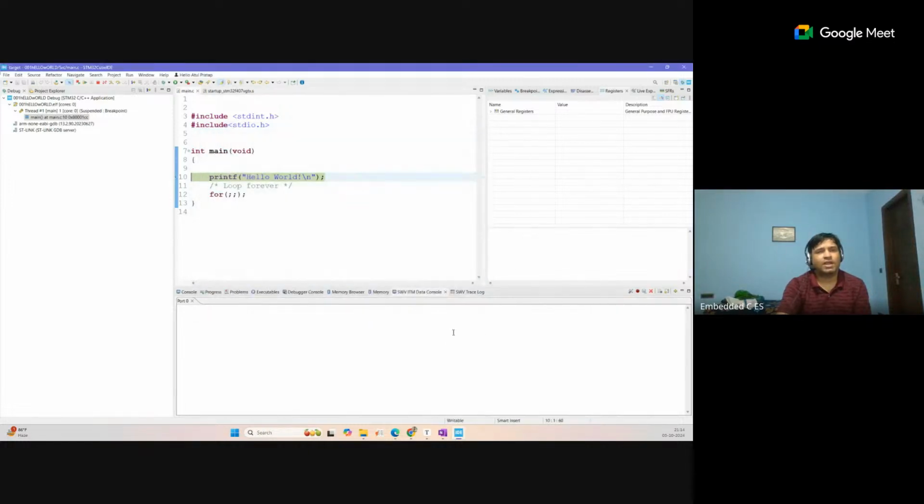After that, if you're not getting any data, you have to start trace here. That is already running now. When you run this code, you can go step by step also. Let's step into. You can see when I step, it moves to the next instruction, the for loop. Now this instruction is executed, this message is passed to our board, so it is now printed.